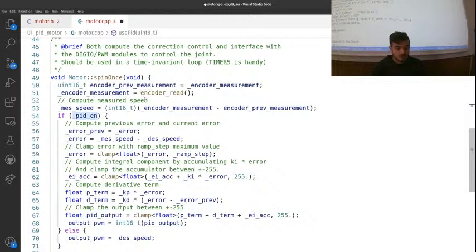Actually, if you want to be precise, we should use locks. When setting the variables, we should disable the interrupt and enable it once we have set the variables. We don't do this for simplicity, but to have atomic reads on these variables, because the AVR is an 8-bit CPU. Whenever we read a value larger than 8 bits, it's going to do multiple instructions, and each of these instructions can be preempted by a potential interrupt. If you're making a car, this is a sensible thing to think about. Otherwise, no. You write a 0 and then you write a large number, and then your car moves very quickly.